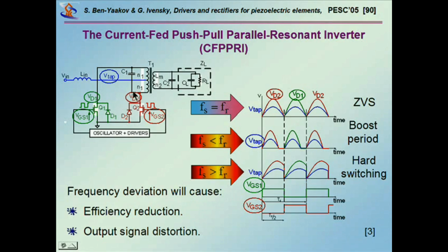Obviously, if the duty cycle is not 50%, then you have a residual DC. However, what really happens is that the waveform will adjust, and you'll have one larger and one smaller swing here, and this will actually compensate for this offset.